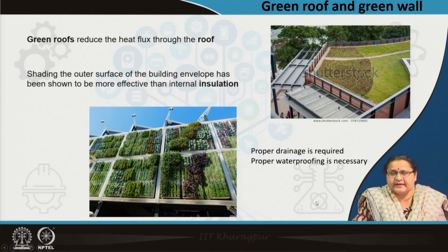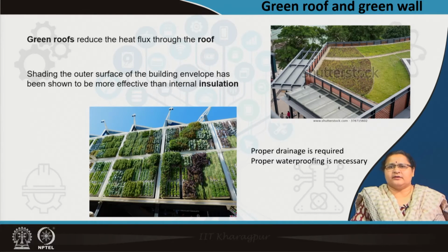But in both the cases, one has to be very careful on the drainage part, otherwise it will lead to damp. Already we have discussed that at length. So, your roof will become a leaky one, it will finally disturb the structural roof and finally it may ruin. Same with the case of the wall, the wall surfaces, you have to be very careful on the roots etc., and also on the water logging.